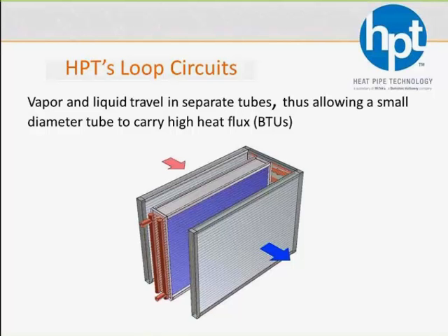We also do something a little bit different. We take that same loop, but instead of sending one end of the loop to another airstream, we'll wrap it around the coolant coil and use it as reheat. So this is what we call a wraparound heat pipe. It's the same loop, except instead of going horizontally all the way across from one airstream to the other, it's just bent into kind of a U shape around the coolant coil. But inside, it's doing the exact same thing.